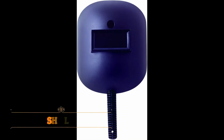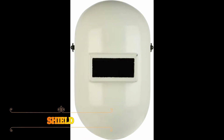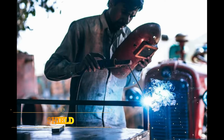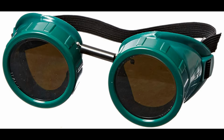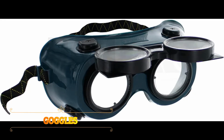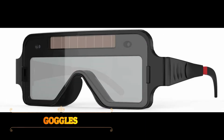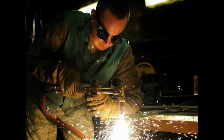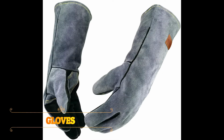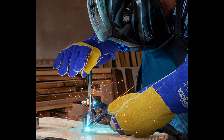The next one is hand screen or hand shield. Hand screen or hand shield are used for protection of eyes and supervision of weld bed. The next one is goggles. These are fitted with colored lenses and are used to protect the eyes from harmful heat and ultraviolet and infrared rays. The next one is gloves. These are required to protect the hands from any injury due to the heat of the welding process.